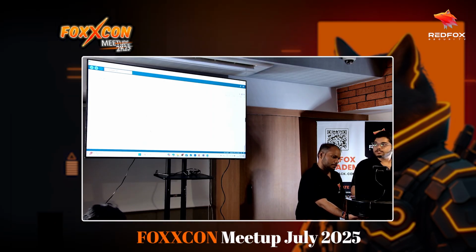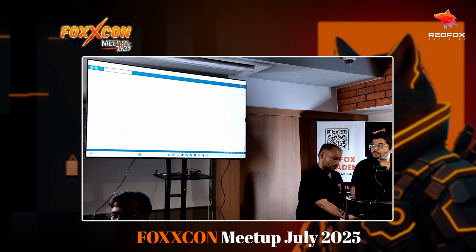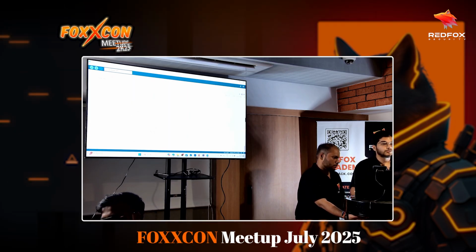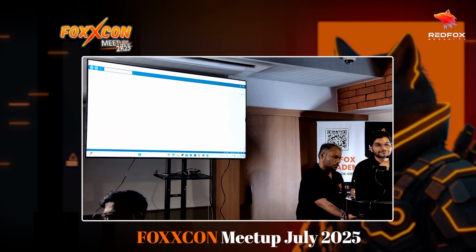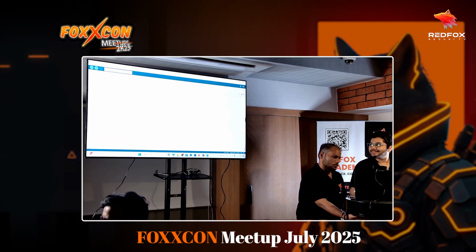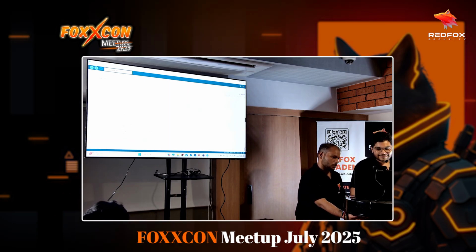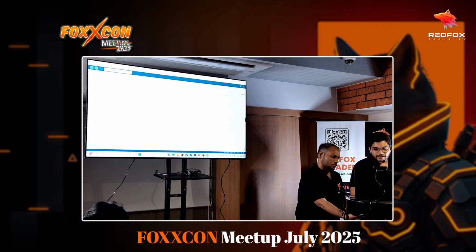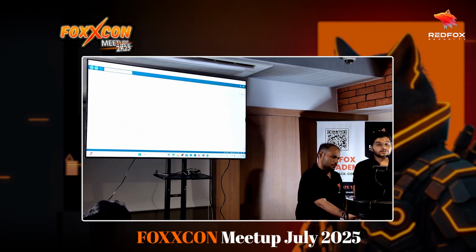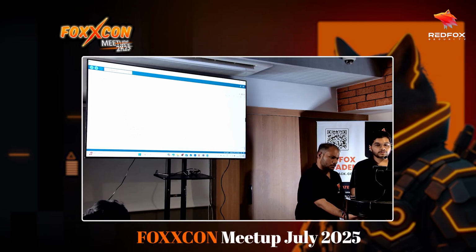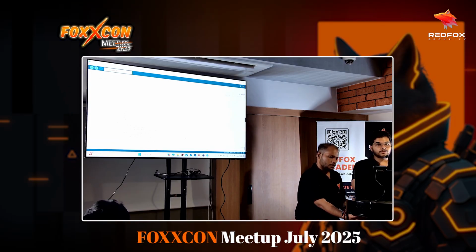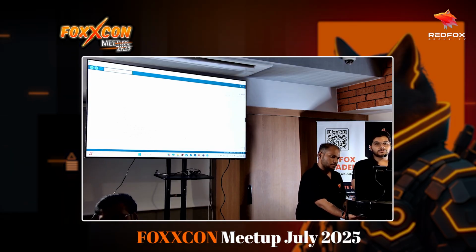These are the logs that are generated when you are looking at how the system boots up. This is what you would see when you're starting up Kali. You might have seen that in common. So yeah, this is what you would see. And as I told you, you can also get a shell via UART. This is just an Arduino IDE opened up with serial communication being monitored.